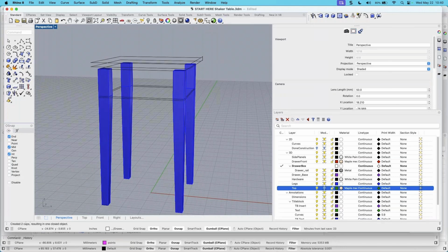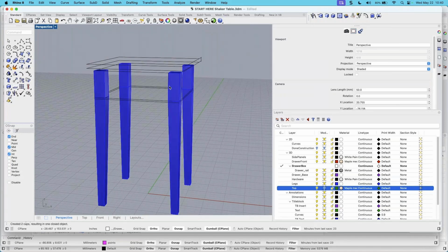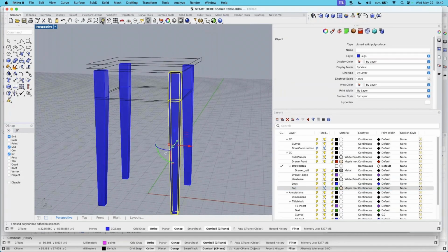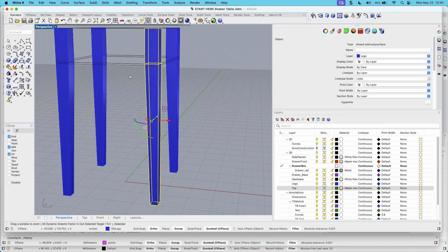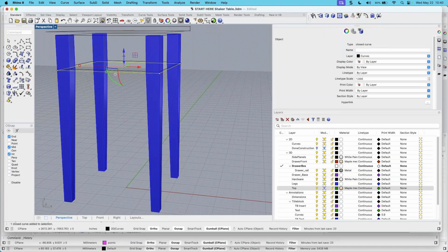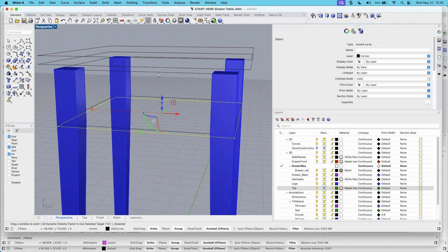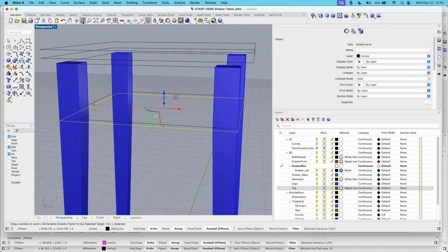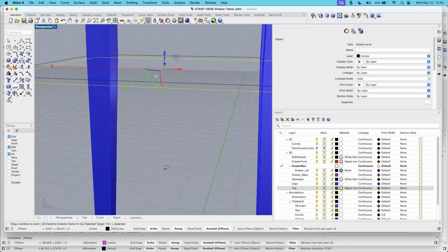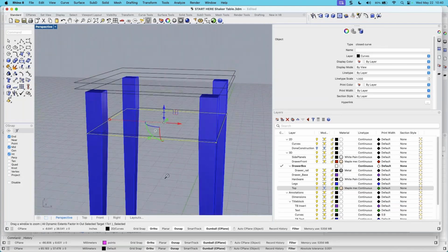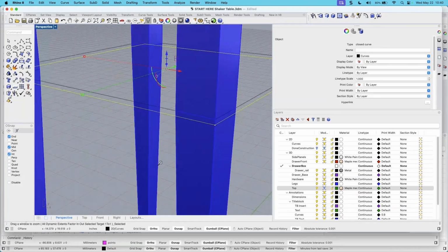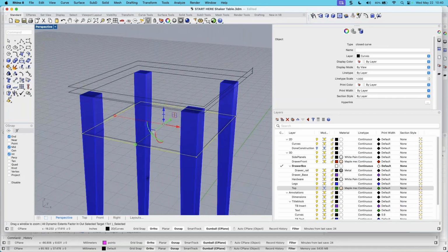What is the command for framing the object you are selecting to do a closer view? If you don't have a scroll mouse, one of the options up here is zoom selected. So if you pick on zoom selected, it will zoom that object into view. It's the one that looks like the yellow one in the magnifying glass. But without a scroll mouse, you can use the command key and your right mouse button. I think that's the easiest way to go if you don't have a wheel mouse.